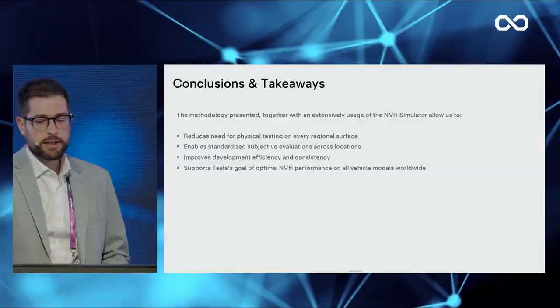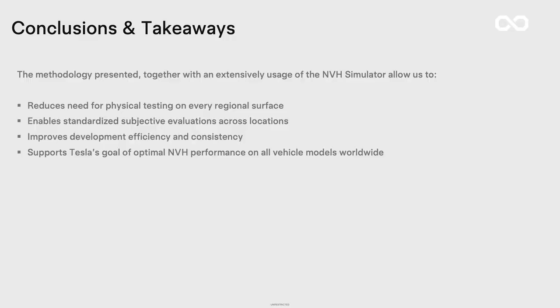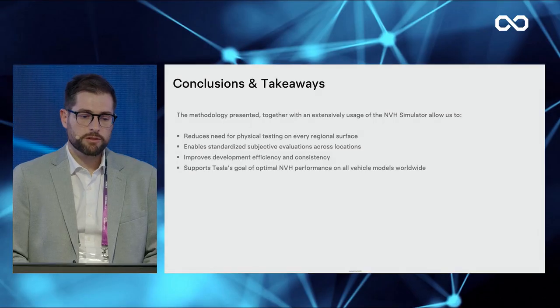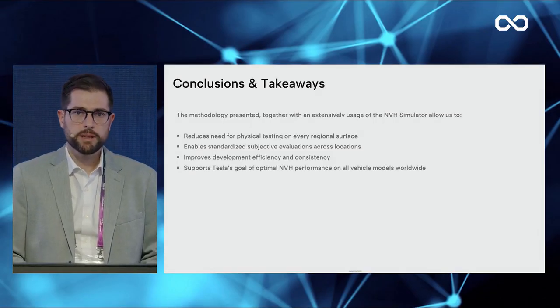To conclude, road surface variation is a fundamental challenge for NVH validation, but combining the NVH simulators with masking noise scaling provides us a scalable and data-driven solution. It improves consistency and reduces the dependency on physical testing across regions, and supports faster and more reliable global sign-off. In the end, we can now predict how a vehicle will sound and feel on any major test track surface that we are using without the need to be there.